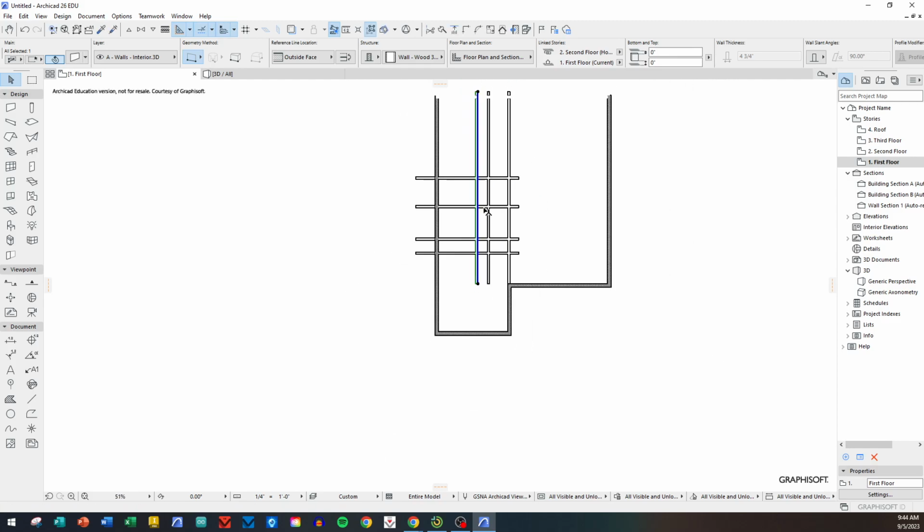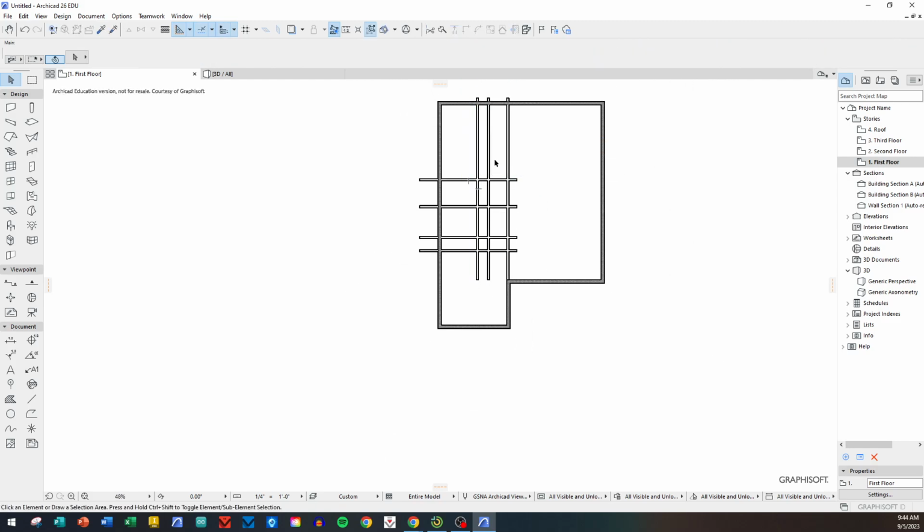Okay, now I can start deleting stuff here. So the trim key works this way. I hold the control key down, and anything I click, see how my cursor turns into scissors? I can trim off. So I trim out stuff that I don't want, like pieces that stick through the outside walls of the house, pieces that stick into bedrooms that aren't supposed to, things that stick into bathrooms or hallways that aren't supposed to, etc., etc. I end up with that right there.